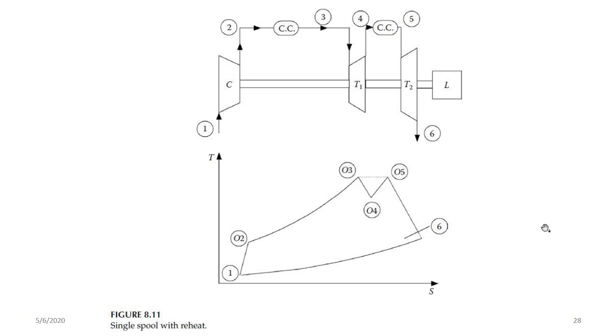And here, you should note that when you design this kind of arrangement, you need to make sure that the maximum temperature in either combustion chamber is the same, because the maximum temperature is a design parameter, like I've always said. You have to know it in advance, because you don't want a situation where the turbine blades begin to deform or melt.